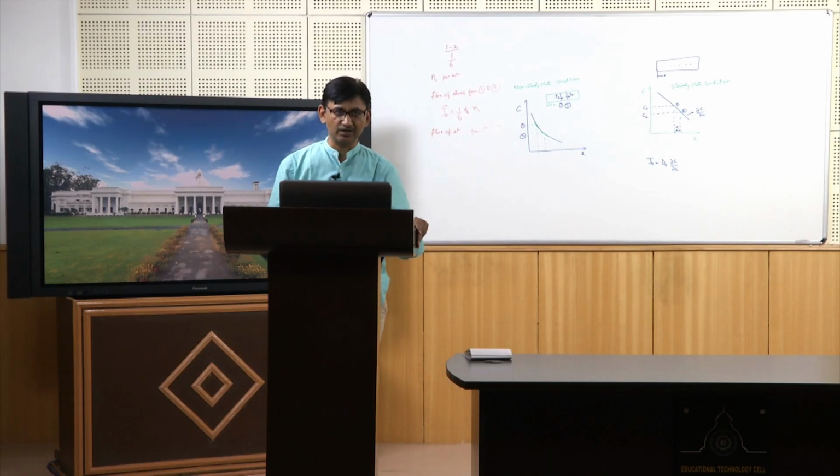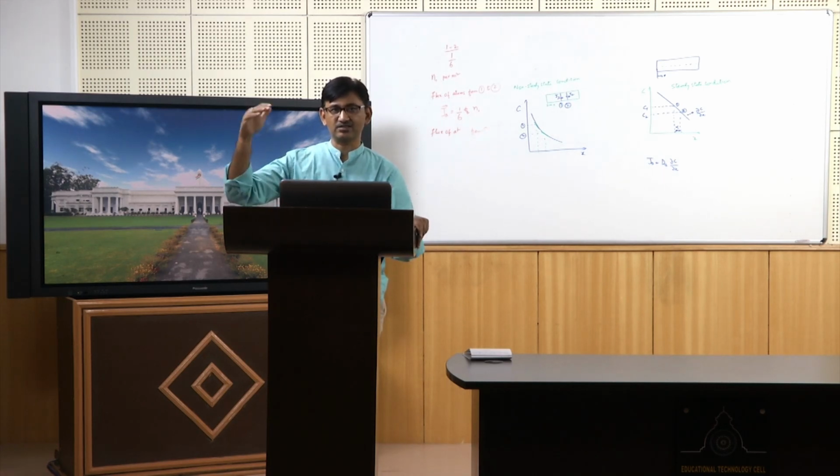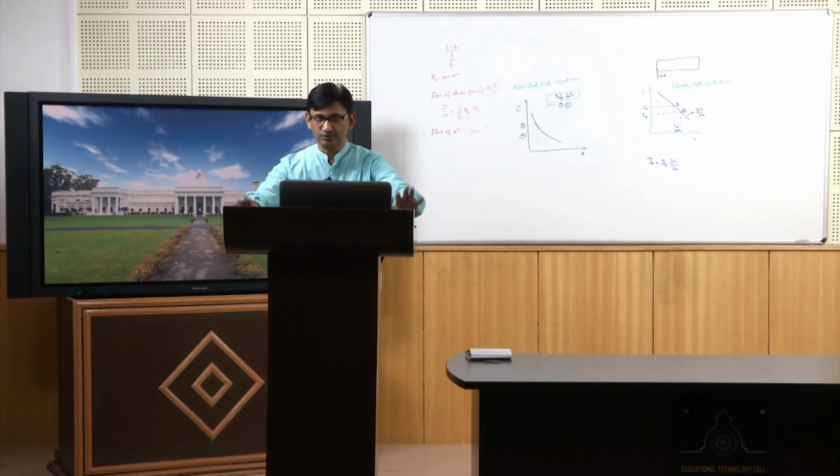In the case of interstitial diffusion, the interstitial sites are always present. In the case of diffusion dependent on vacancies, you can understand that vacancy concentration is a strong function of temperature; it increases exponentially with temperature. So where you need vacancies, the diffusion process will depend on both the ability of an atom to jump from one site to another and the creation of vacancies to do that. Both come together to have any diffusion.